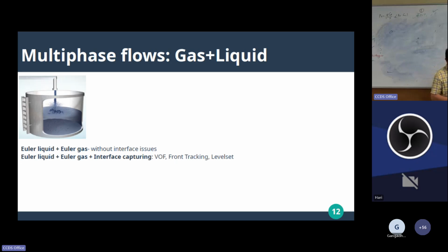It's not like typical fluid mechanics where you have the Navier-Stokes equation. I can write the momentum equation even at each point by control volume analysis and try to really link it up. It is not that straightforward in multi-phase systems, even for solid-liquid. And you will see this kind of multi-phase system in engine chambers like gas turbine engines and other things, as the most prominent feature.